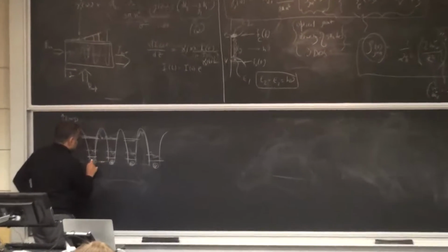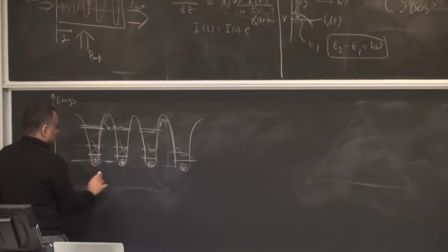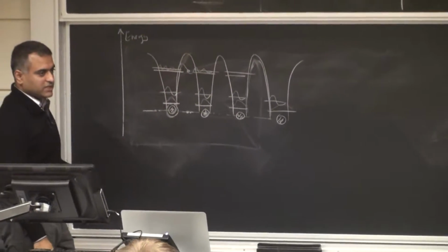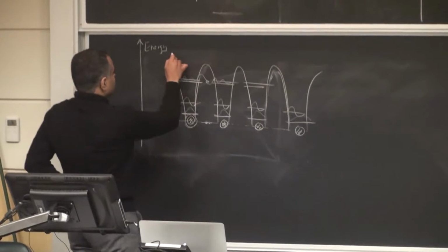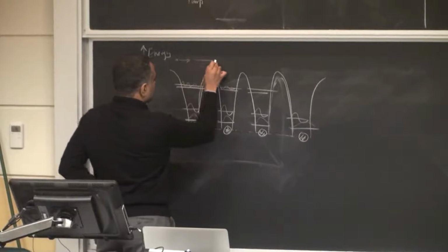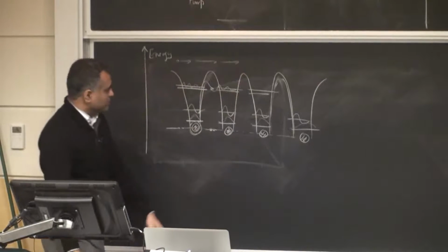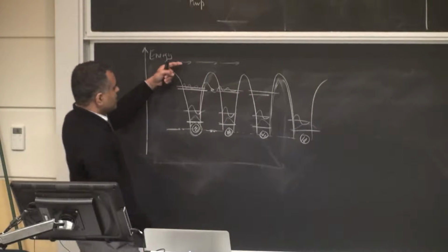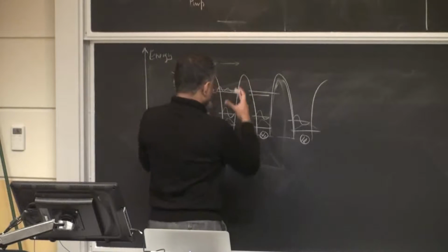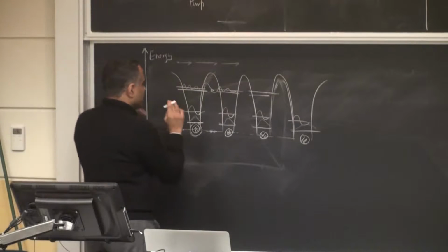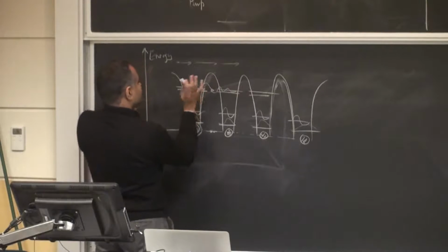So the same electrons that form the chemical bonds will form what we are going to call the band structure of the semiconductor. And then if your electron energies are much higher than these potential minima, they will go through. These would be high energy electrons. If you shoot a 1 kilo electron volt electron through a semiconductor crystal and it's thin enough, you can go through without really getting captured anywhere. It's possible, right? But we are not going to look at that. We are going to look at low energy excitations.